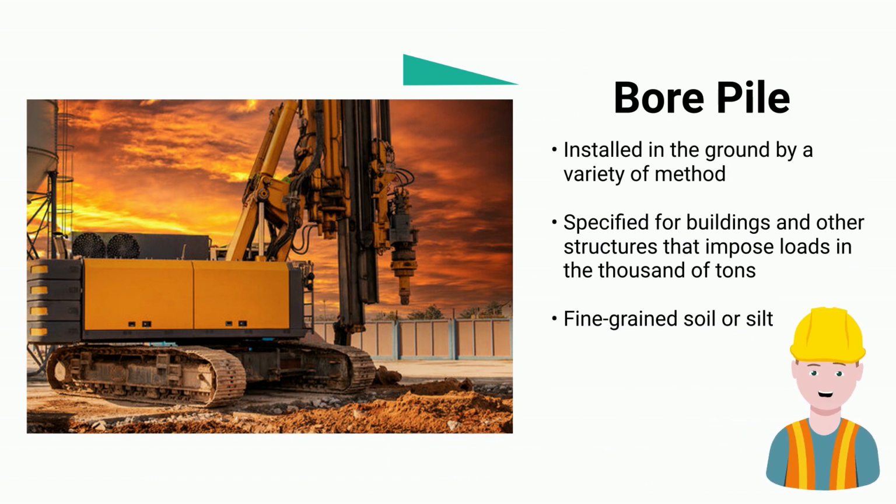Bore pile is installed in the ground by a variety of methods. It is specified for buildings and other structures that impose loads in the thousands of tons. Bore pile is suitable for fine-grained soil or silt soil condition.